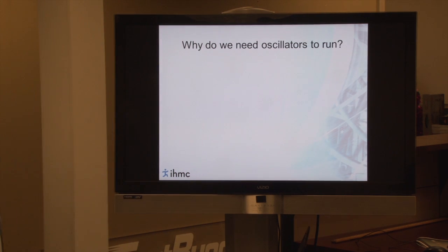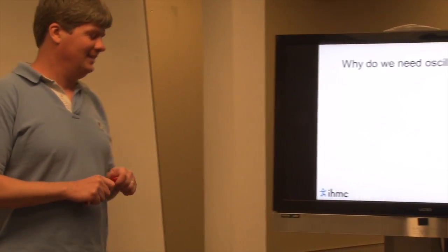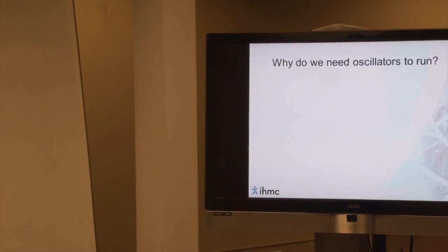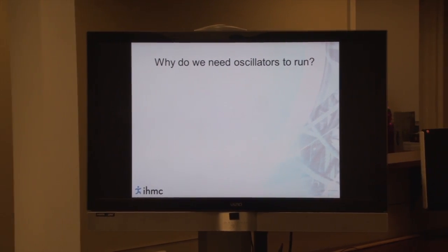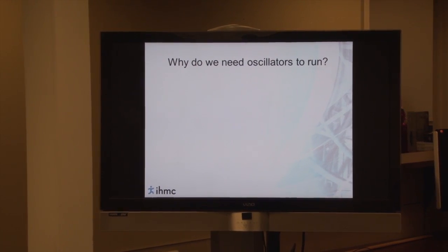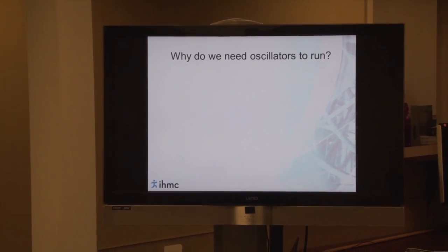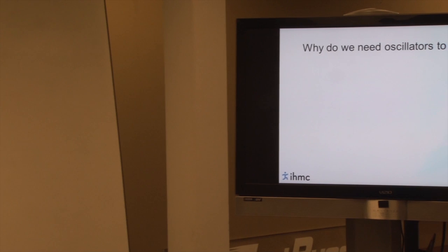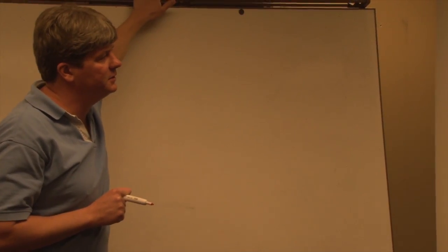Okay, so why do we need oscillators to run? Efficiency and power requirements. If you have a leg that's moving back and forth, it needs to accelerate and decelerate frequently. If you're trying to do all of that with a motor and a controller, you're going to just be dumping power into it and need a very powerful motor. If you have an oscillator on it, then it does so with much less energy usage and therefore much less energy waste. Okay, so those are advantages of using particular types of oscillators.